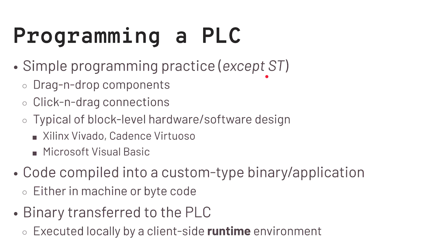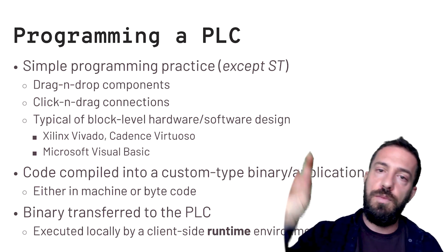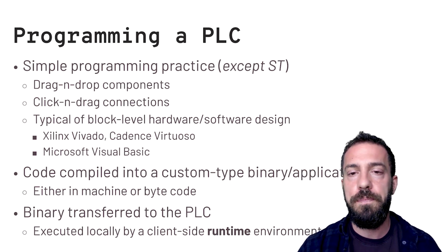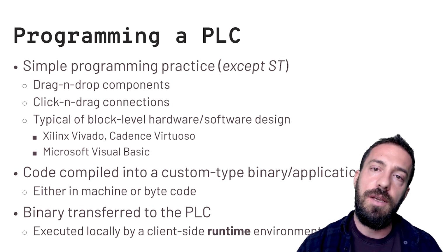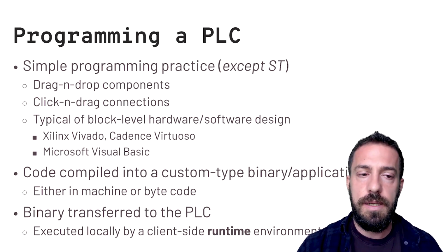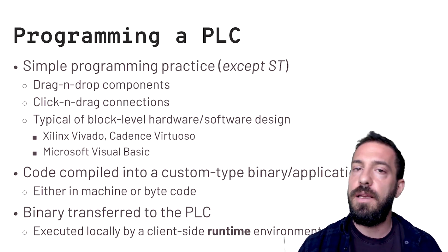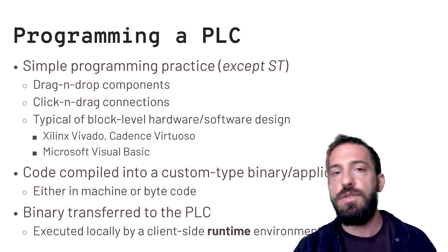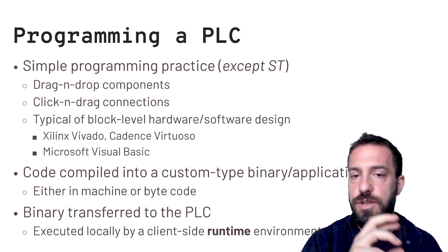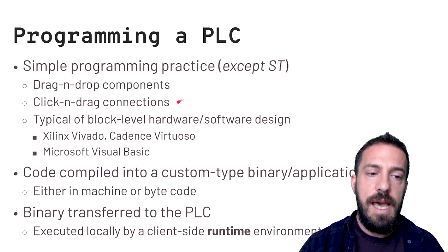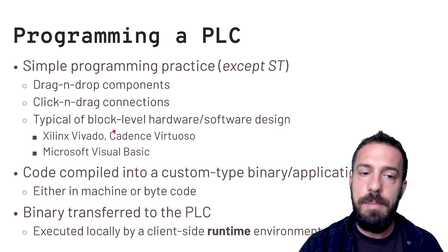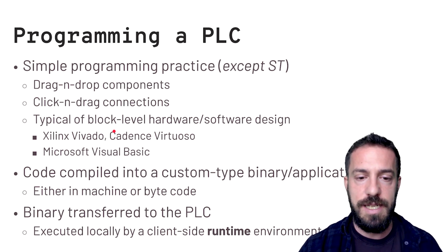So to program a PLC, with the exception of structured text, it's more of a drag and drop environment. As we saw, most of the languages were visualized. So you take your function blocks, you bring them into your IDE, to your test workbench, and you connect them. You bring your absolute function, your minimum function, your limit function, and you connect them with wires. And this resembles a typical block-level hardware or software design.